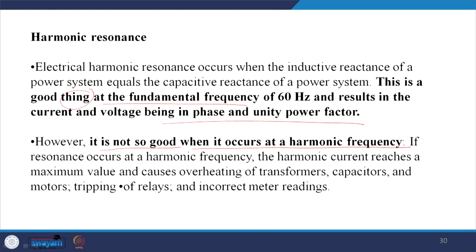If resonance occurs at a harmonic frequency, as I was discussing, the harmonic current reaches a maximum value and causes overheating of the transformer, capacitor and motor, tripping of relays and incorrect meter reading. Because these meters are calibrated for sinusoidal operation, if you feed a non-sinusoidal voltage and current, it will not give you the proper reading.